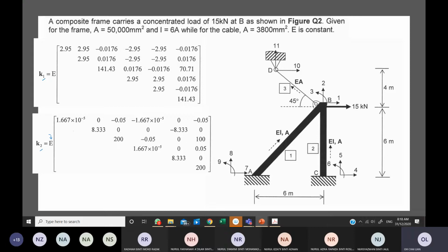For example, we need to know that in a beam, we can determine the shear force and bending moment. The axial effect will be obvious if you have a lateral loading. If not, we don't normally find the axial force. For a frame, we have the internal forces like shear force, bending moment, and the axial force. For a cable or for truss elements, we have only axial force. We don't have any shear force, and we don't have any bending moment.